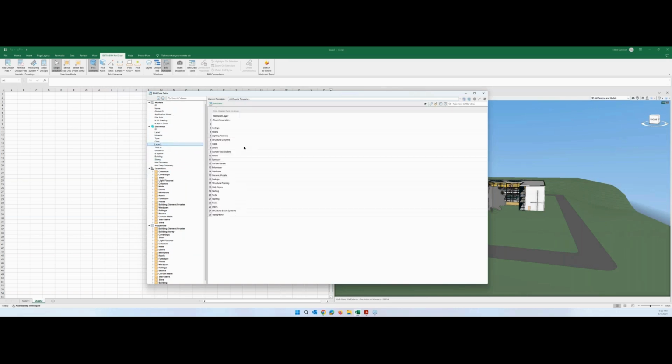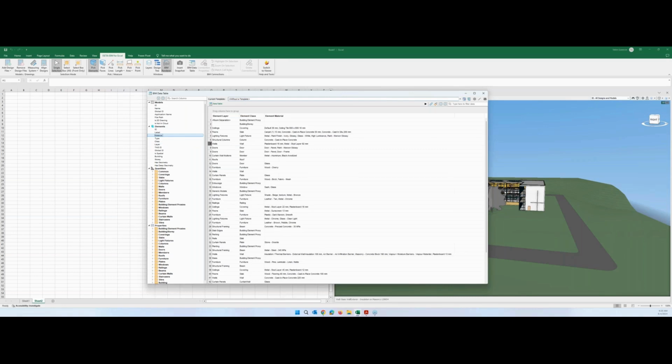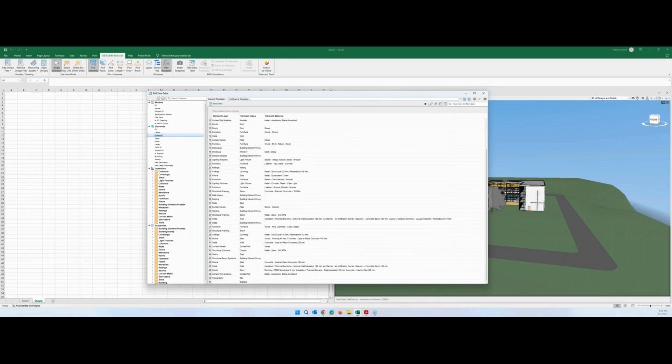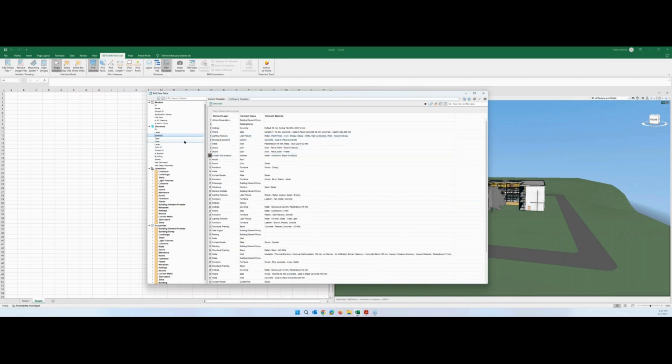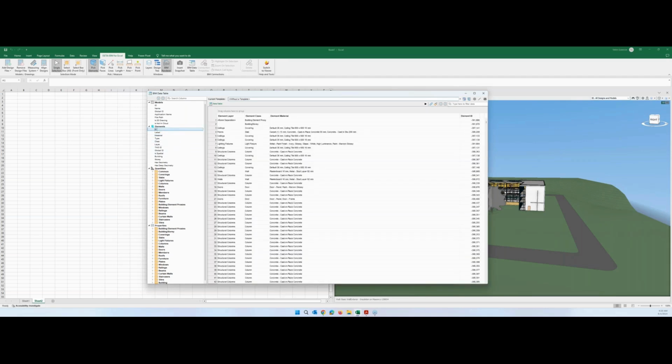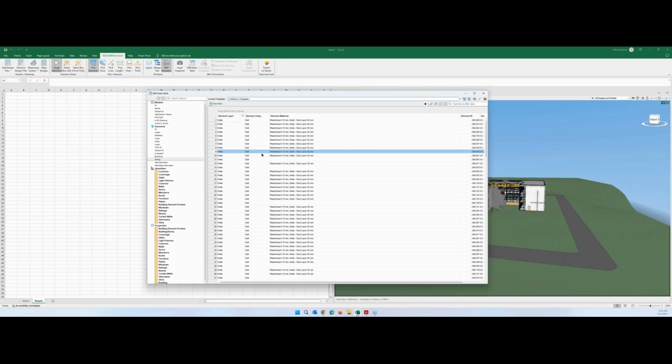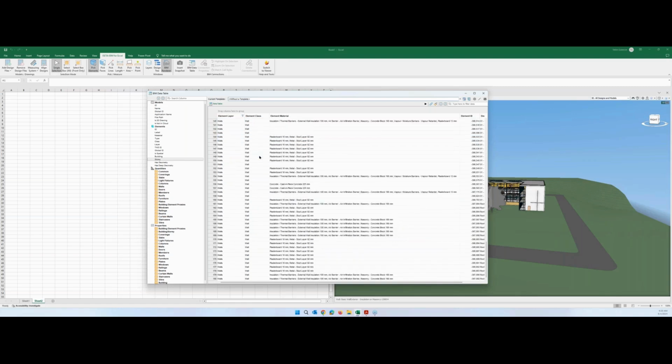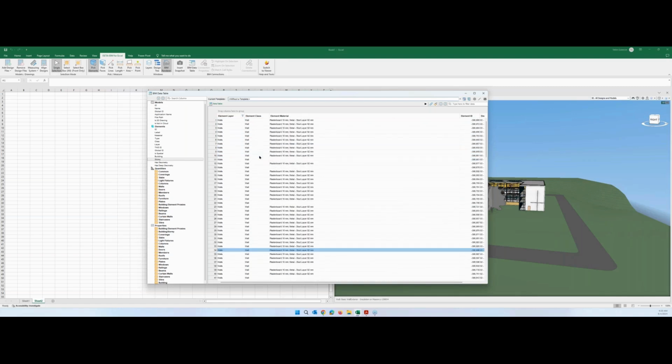layers. I can see that these are the layers available, and I can put here, for example, class. I can put here, for example, materials, and you can see that all the parameters are coming here. I can put here ID, and I can put here, for example, floor level. And let's focus on the wall only at the moment. I would like to get, for example, only walls. And these are all the walls available in my project, okay?